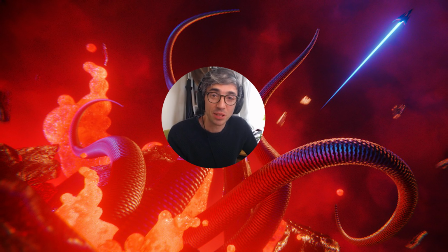The reason why we're doing that is because I want to have some splines in my scene that are kind of curvy, like tentacles. And splines come with UVs already mapped out that follow the surface of the spline itself. So if we make something that works using a UV, it's going to naturally follow the flow of the surface of our object. So UV is going to be really good for that.